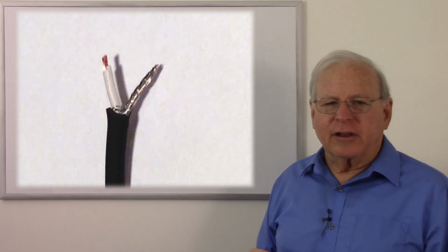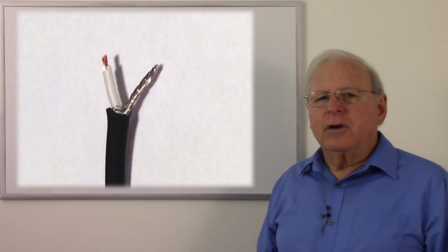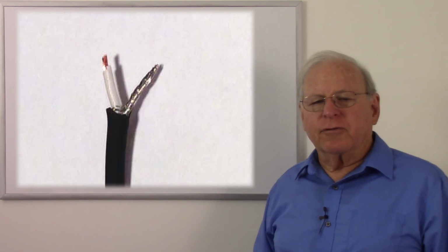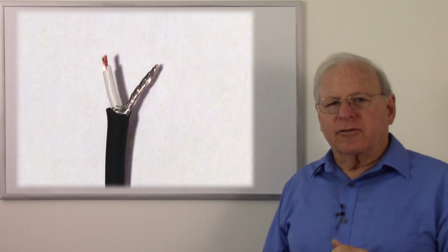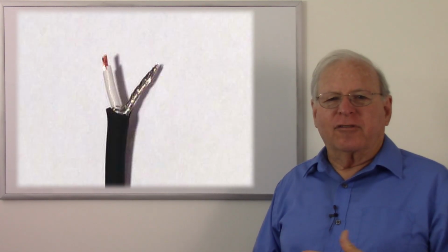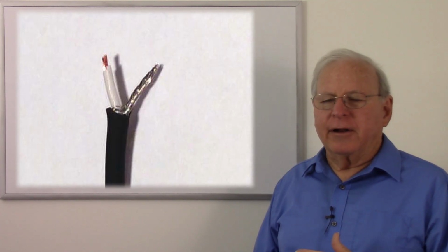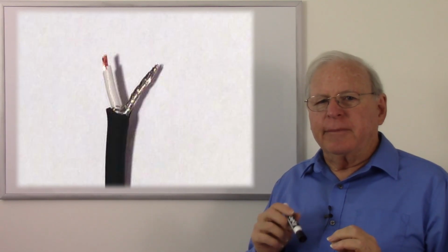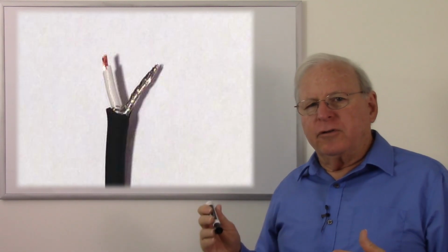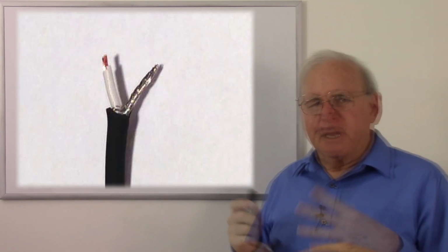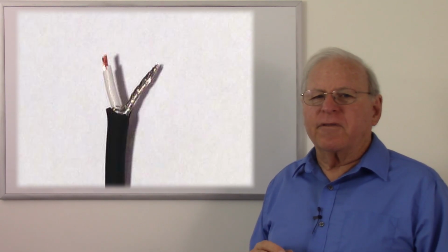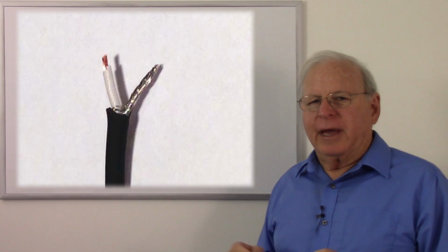This is an unbalanced signal, but we might have two wires, maybe a twisted pair inside the shield, especially for long runs with microphones, so that we also have the inherent noise canceling of the twisted pair, which I talk about in other places. So we want to have shielded cable to eliminate noise going from the pickup to the preamplifier, because if we pick up any noise there, that noise gets amplified. So we need to make sure we have a very low noise system at that point.